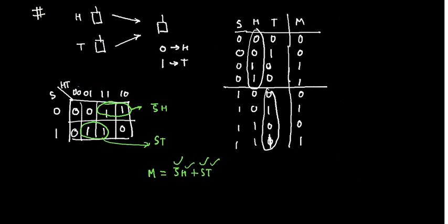How many inputs are there? How many selection lines are there? It is a scaled version of this one. Yes. So this is a 2:1 multiplexer, right? Isn't it? Because here the inputs are only 2. You can do that, but you have to receive the result, and only one person is receiving the result. A multiplexer is a device which is having only one output. You can't have two outputs, right?